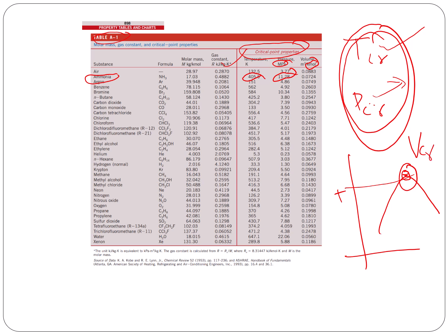That's how we get it using the equation. So just be careful with this one, okay? You can directly use the values of critical temperature and pressure from this table. For the specific volume, we can use the temperature and pressure relation to find it.